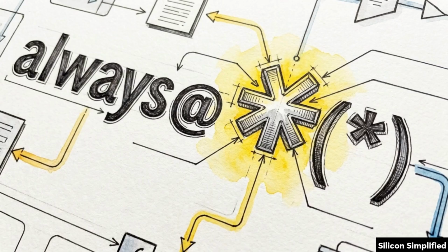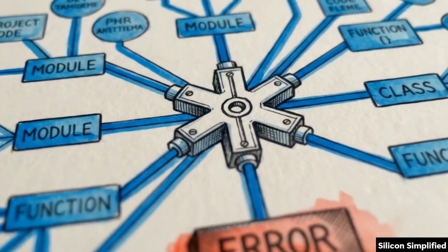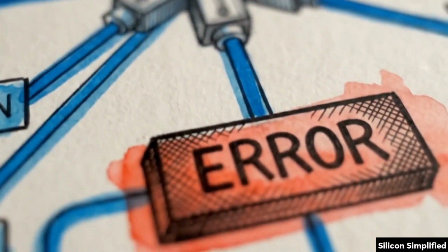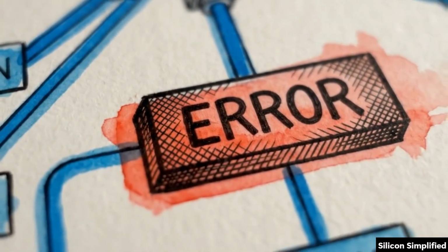To stop this simulation mismatch, the Verilog 2001 standard introduced the always @* auto-populating list. The wildcard asterisk tells the tool to automatically include all right-hand variables. But while it fixed list omissions, it masked a more subtle structural error.